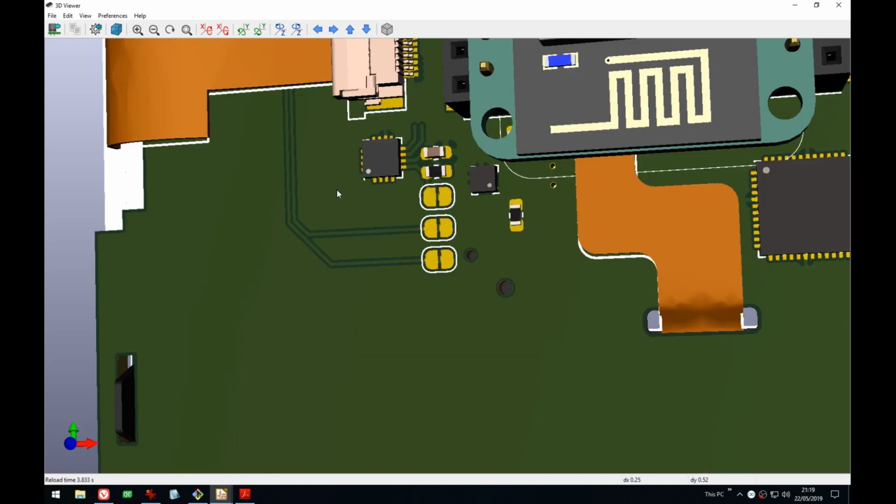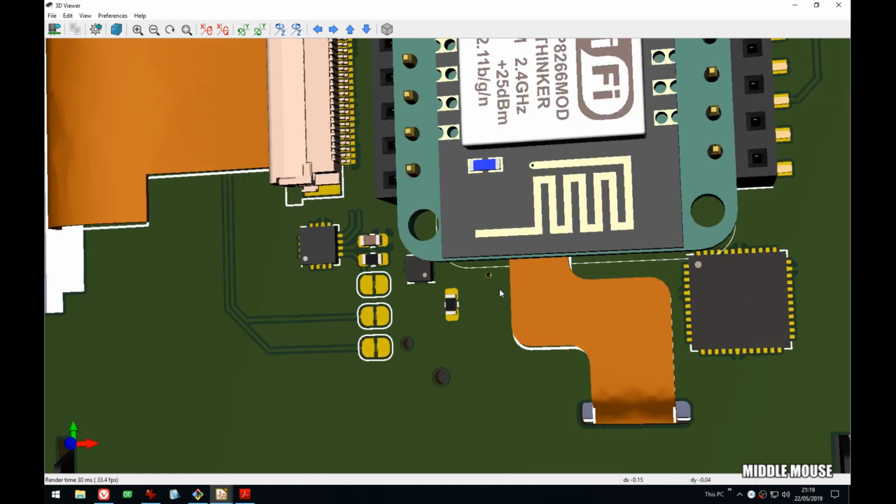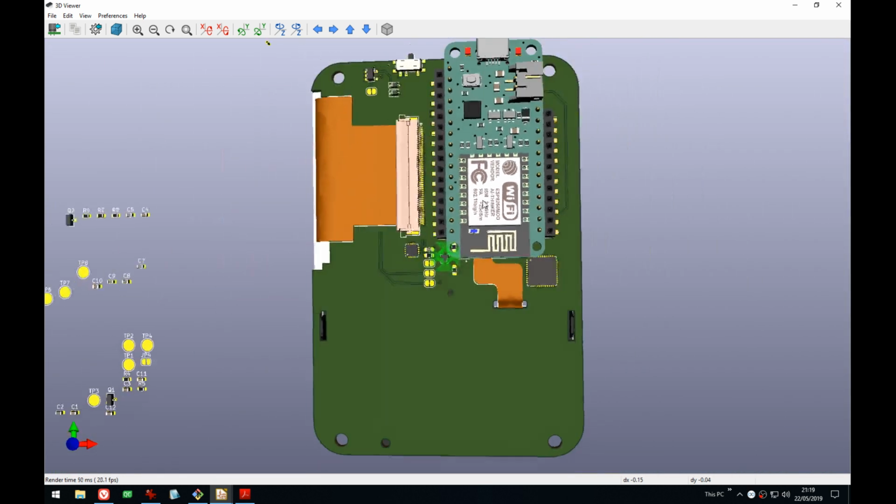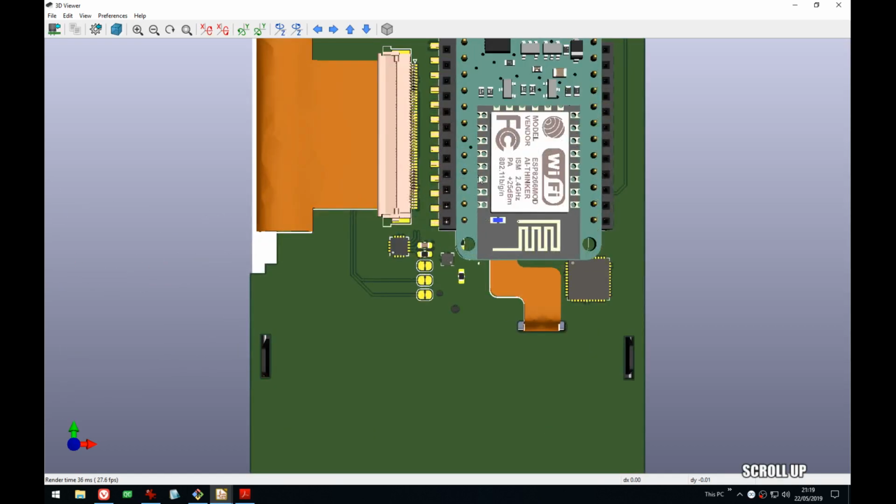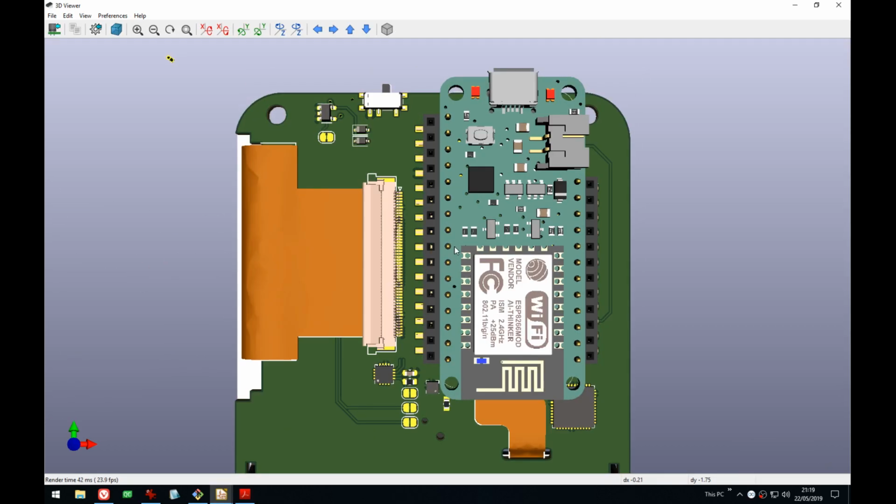So for LDOs, for example, LDOs are fairly easy to choose. Obviously you need the voltage that you want to get out of it. There's actually no LDO here because it's on the Feather, but you need to know what goes in, and that can be a range from, let's say, 5 to 9 volts, and then out you need 3 volts.